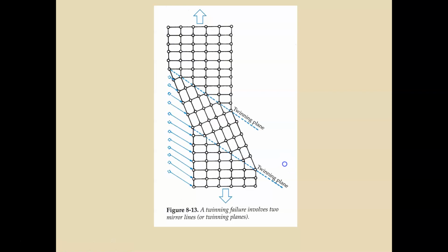So mechanical twinning occurs in metals that have body-centered cubic (BCC) and hexagonal close-packed (HCP) crystal structures at low temperatures and at high rates of loading, otherwise known as shock loading, conditions under which the slip process is restricted. They are more likely to form deformation twins when strained because they rarely have a sufficient number of slip systems for an arbitrary shape change.